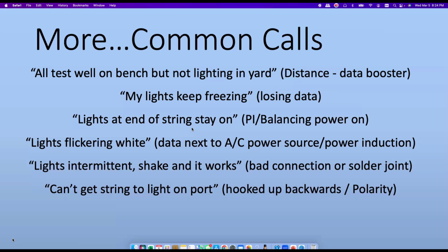So I reset my controller, made sure the ports were right and all that, and then shut them down all the way, removed the power injection and reconnected it, and it cleared it out. I eventually had to replace the string of pixels that was having a problem because it kept happening and I just don't have time to deal with it when that stuff starts happening.